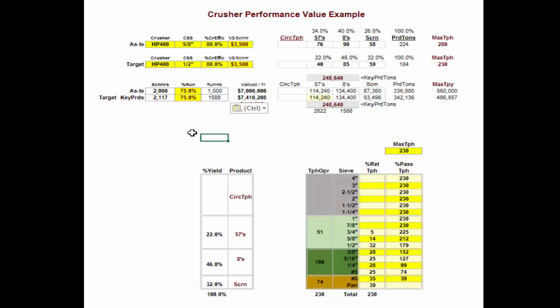You see it actually takes more hours, not many more, but it takes more hours because the ton per hour drops. The capability of the crusher to produce material or feed material through it reduces as you close the setting, and again it drops to 175 tons an hour from 280 tons an hour.